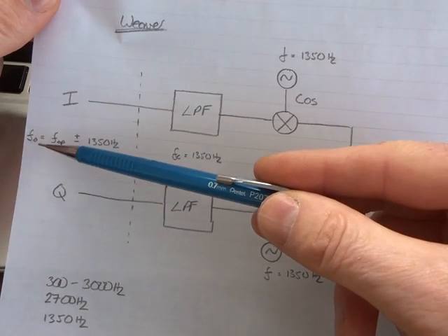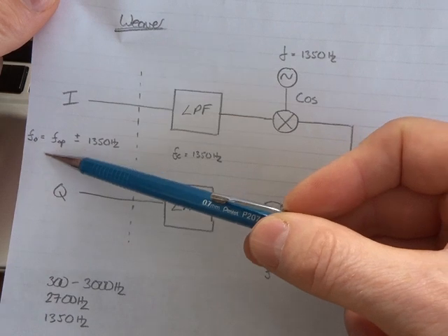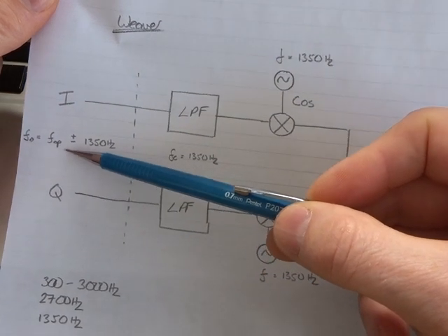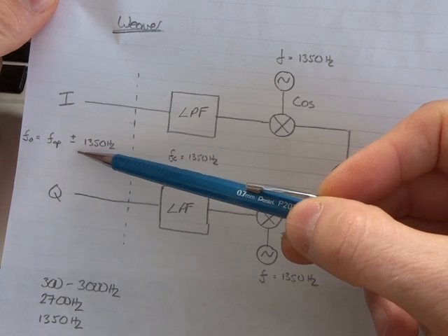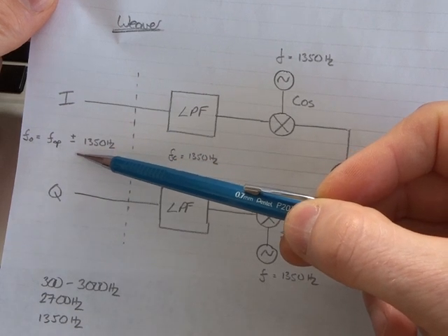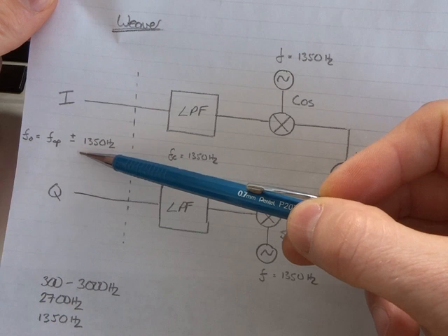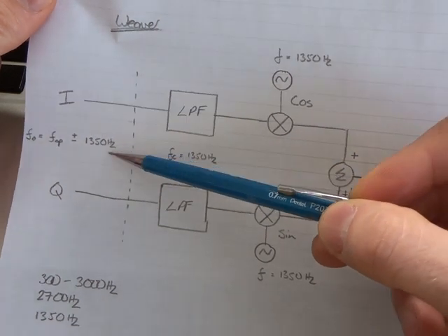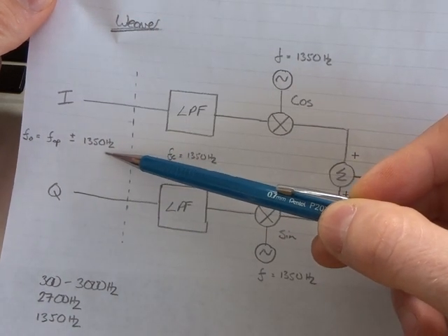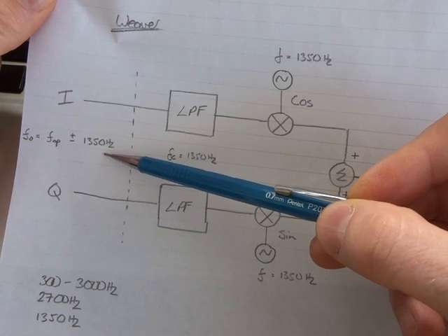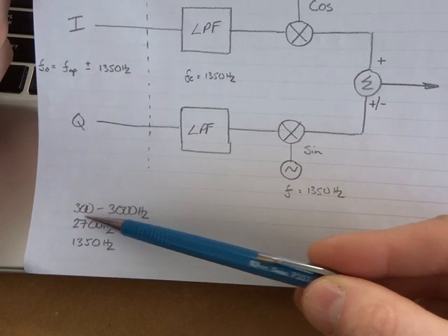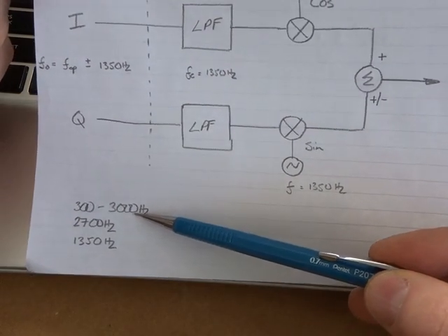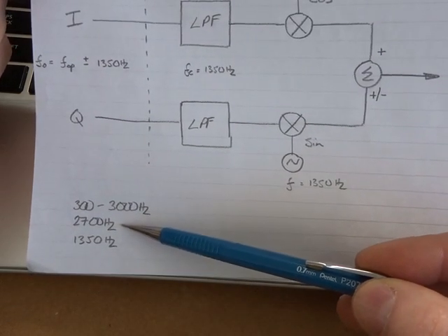But interestingly, for the SI5351, you need to set it to be your frequency of operation in either plus or minus, depending on whether you want to recover the upper or the lower sideband, plus half of your desired audio spectrum. So if we were to have 300 Hertz to 3 kilohertz, that's 2700 Hertz total.